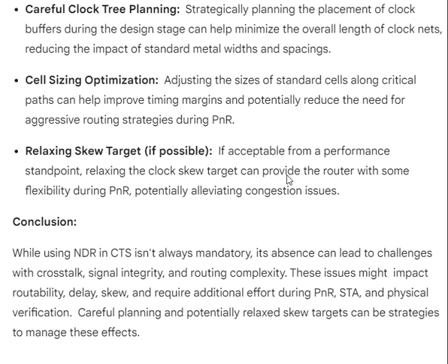Conclusion. While using NDR in CTS isn't always mandatory, its absence can lead to challenges with crosstalk, signal integrity, and routing complexity. These issues might impact routability, delay, skew, and require additional effort during PNR, STA, and physical verification. Careful planning and potentially relaxed skew targets can be strategies to manage these effects.